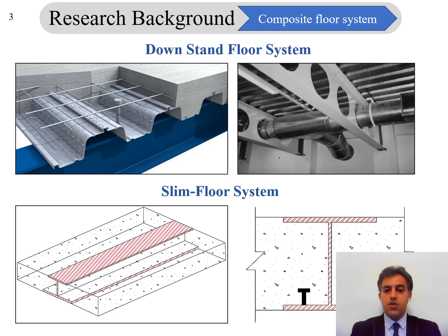In this system, ducting and service pipes run through the web openings provided in the web of the steel beam. The slim floor system is proposed as an economical system, with a lower floor slab depth where the slab is supported on the lower flange, which eliminates the use of downstand beams and gives a flat look to the slim floor system.